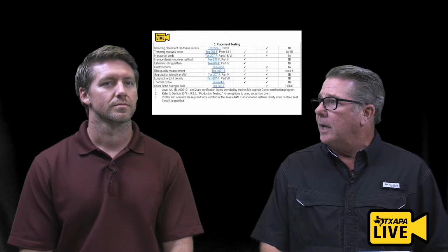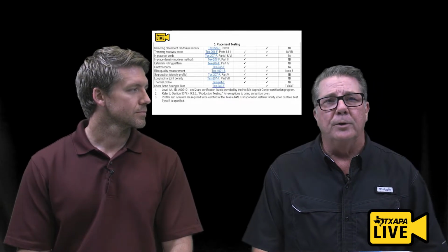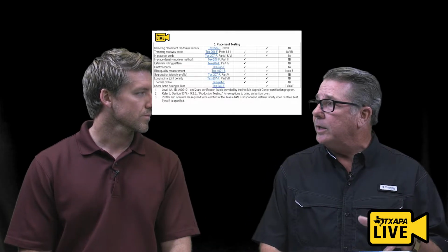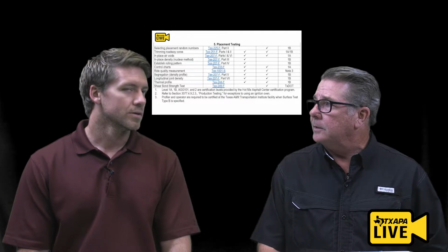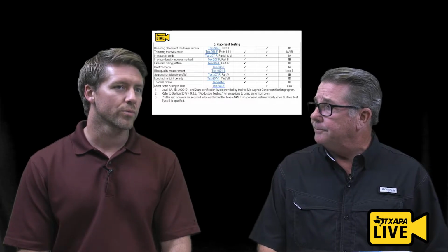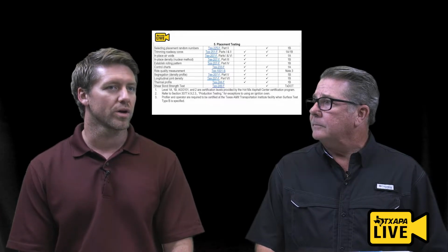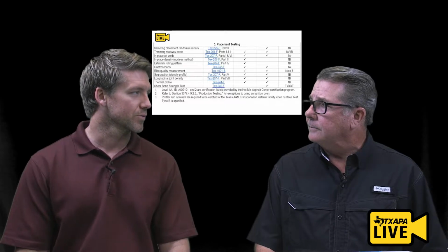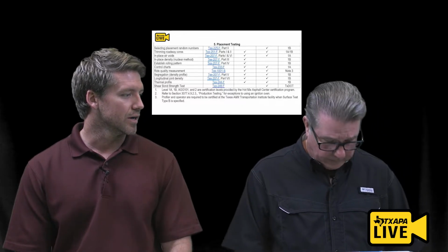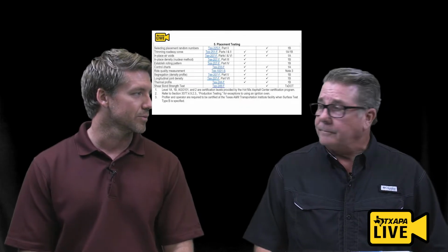And then, of course, we have the shear bond strength. That's a test that only MTD can run. It's informational purposes only, but I do know that several districts are really looking at trying to establish some minimum shear bond strengths. So you guys have been running a lot? So we run quite a bit. Keep in mind right now this is an informational test. There are quite a few districts that have actually set up to run it as well. So I know Austin District, for example, has their own database that they're maintaining, and they require informational shear bond test on every project.